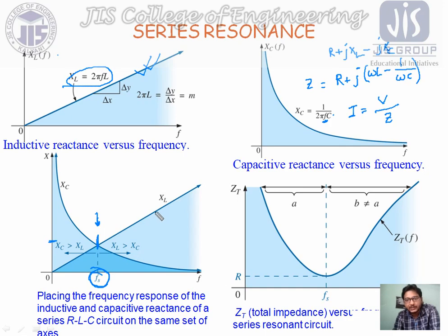Suppose we consider a particular frequency, let's say Fx, where the inductive reactance is much greater than the capacitive reactance. So obviously at this frequency the circuit will have an inductive effect, and the circuit will be lagging.